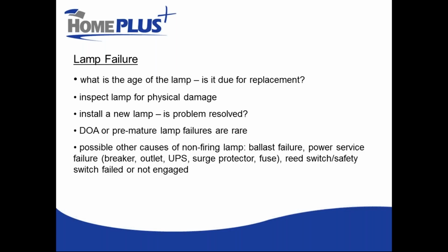I kind of rushed through this and I apologize, but essentially chlorine does not work instantaneously. UV light does. As soon as the water's passed through the chamber, it's done its job. It's very quick. But chlorine is not very fast. It takes time. So after we add the chlorine, we have to put the chlorine into a contact vessel and give it lots of time to do its job.